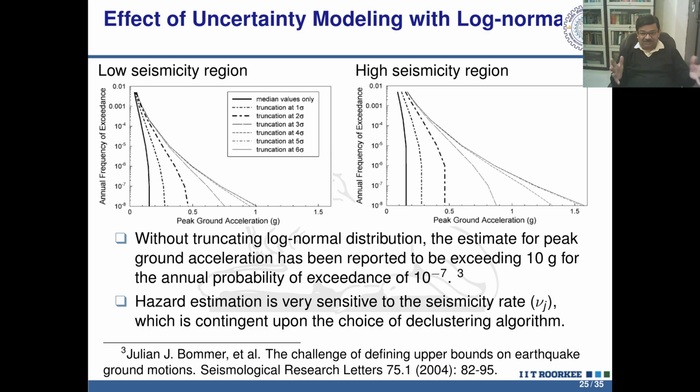Design earthquake ground acceleration, peak ground acceleration. Obviously, that is impossible. Because the lognormal distribution is a mathematical model, it has no constraint coming from physical limits. The energy release is finite, and material strength to accommodate that much strain is also finite. It cannot accommodate infinite strain, so it will rupture much before energy corresponding to this kind of ground acceleration can ever be accumulated.